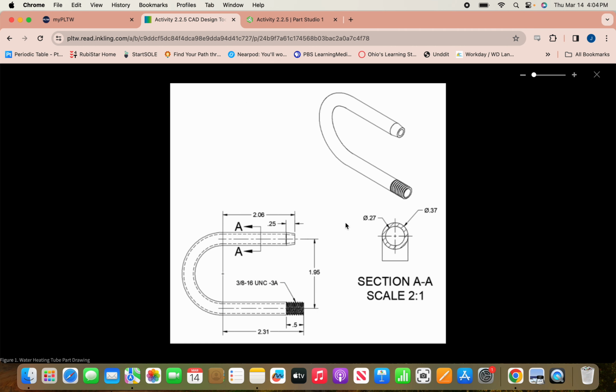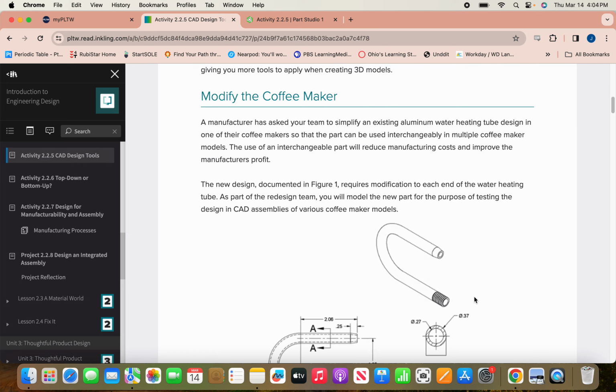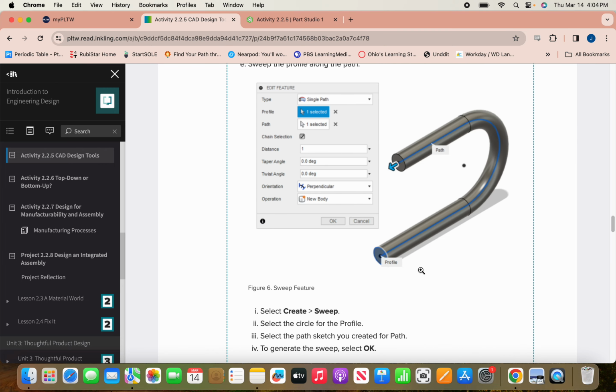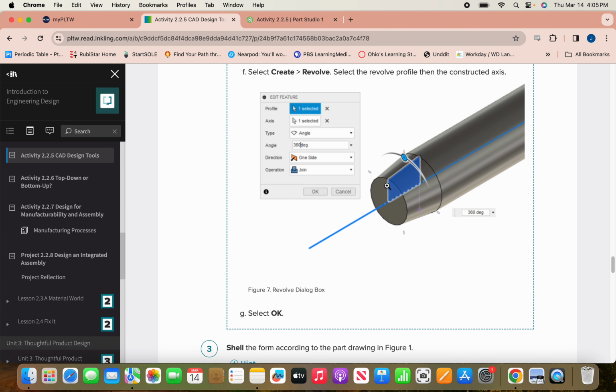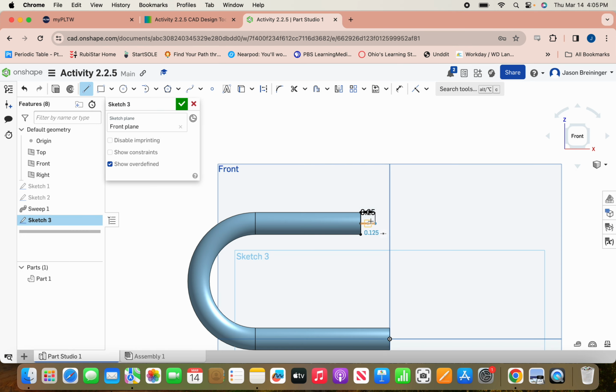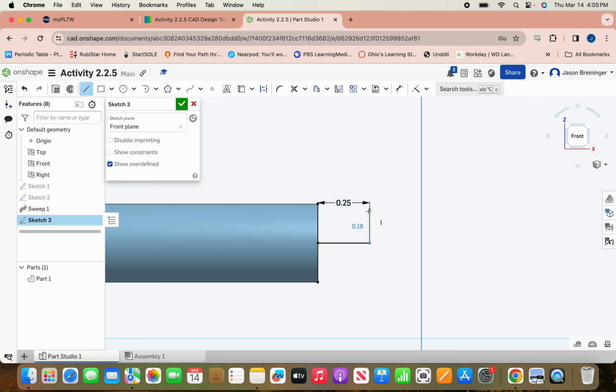Now the part that I need in order to make this taper, right? I'm going to have to kind of guess how far up I want this edge to go that I'm dragging now. They don't really tell you. I'm going to make mine 0.125, which is 1/8 of an inch. So yours should be 0.125 as well.